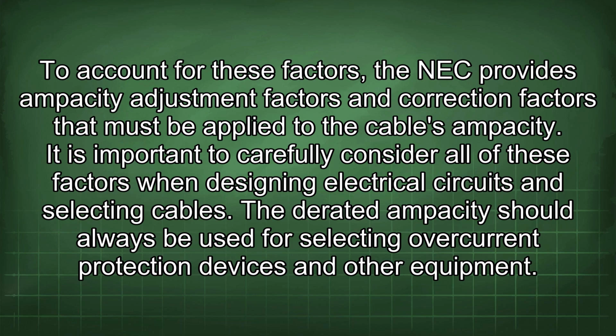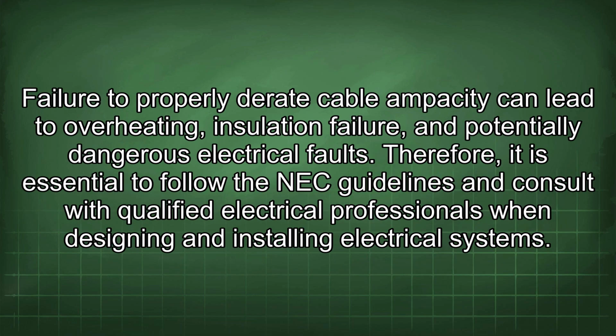To account for these factors, the NEC provides ampacity adjustment factors and correction factors that must be applied to the cable's ampacity. It is important to carefully consider all of these factors when designing electrical circuits and selecting cables. The derated ampacity should always be used for selecting overcurrent protection devices and other equipment. Failure to properly derate cable ampacity can lead to overheating, insulation failure, and potentially dangerous electrical faults. Therefore, it is essential to follow the NEC guidelines and consult with qualified electrical professionals when designing and installing electrical systems.